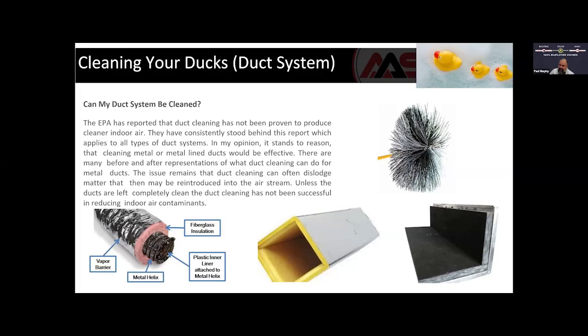The next one in the middle there, the yellow one, is your typical duct board that you'll find throughout buildings everywhere. It is an exposed insulation or fiberglass made of just a fiber board that's glued together and a vapor barrier. Inside there, again, your duct cleaning brush can disturb that fiberglass and then make it airborne again. So that's another reason we don't recommend cleaning fiber duct board as well.